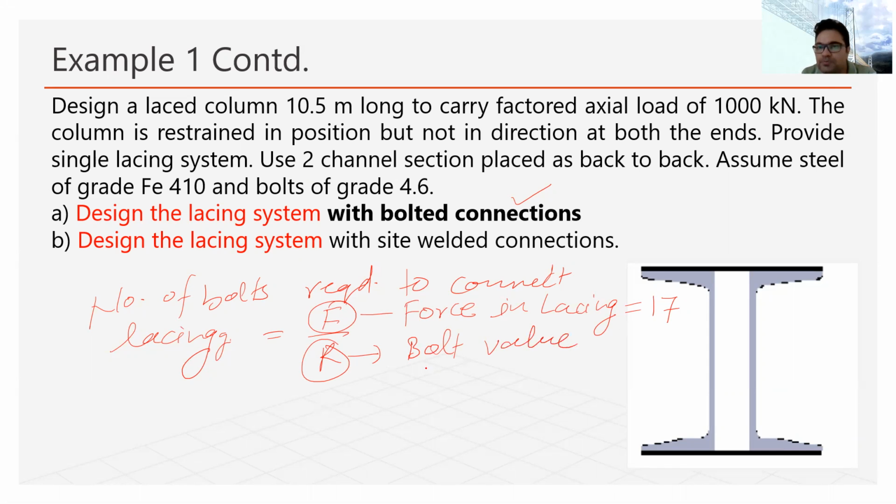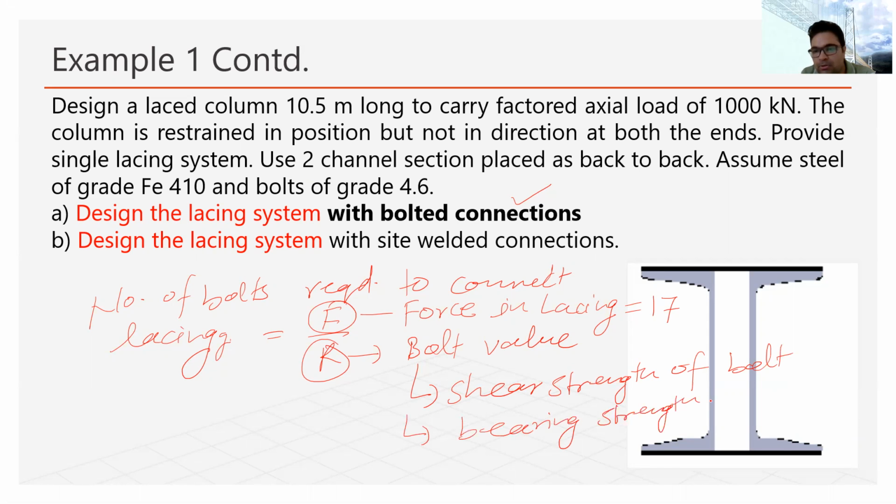Now bolt value, I hope you remember, bolt value is actually the least of shear strength of bolt and the bearing strength of bolt.